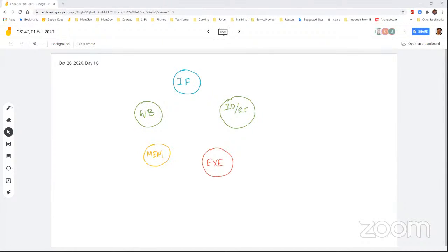It starts from instruction fetch at the very beginning, and this state machine, per clock, cycles through these states. And each state is using some of the hardware components. This stage is almost related to your memory, the instruction part of the memory is accessed and being read. Whereas instruction decode and register fetch is more utilizing your register file, it is reading from here.